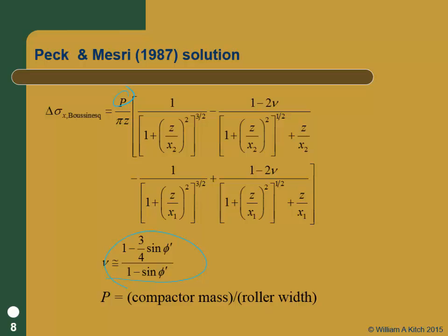So another nice thing I like about this is, if somebody's concerned about it and comes to you and says, how big a piece of compaction equipment can I put behind there? You can say, well, I don't want the loads to be higher than this. You can go back there in half an hour, you could have a calculation and say, well, don't use anything higher than 20 tons or something like that.